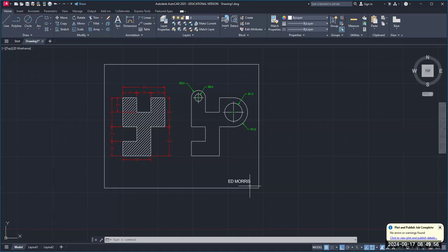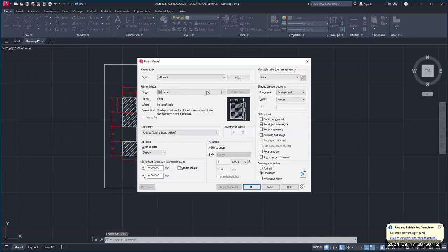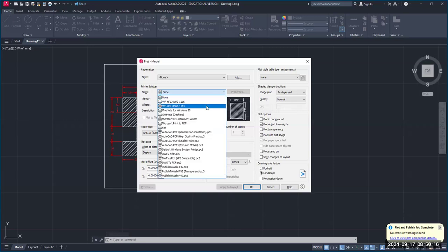All right, you're going to do a plot. Type in plot. Yes. You have to speak louder. How to print? Yeah, I'm getting ready to do that now. Type in plot. Enter. Select the name of your plotter. But this time, if you're going to print it out on the printer here, this is our room number 1113. Click on that.